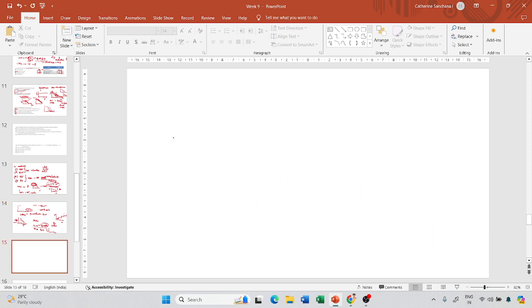This also you will do in a parallel plate system at temperatures of 50, 60, 70 and 80. Here phase angle means what? It has to have a frequency loading, an oscillatory loading has to be applied on the sample, right? So here you will do a frequency sweep, which means your parallel plate, your top plate will not keep on rotating, but it will oscillate back and forth. So I will do a frequency sweep from 0.001 to 100 radians per second, okay.